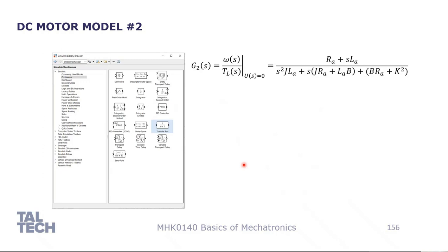So all those transient processes, if we know how to describe them, if we know the mathematical background, we can represent as a function, a so-called transfer function. If we know exactly the parameters of the electrical machine, you can see in our transfer function here we still have the values that we are getting from our electrical machine. Sorry, so we have here the armature resistance, armature inductance. Inductance here is very important.